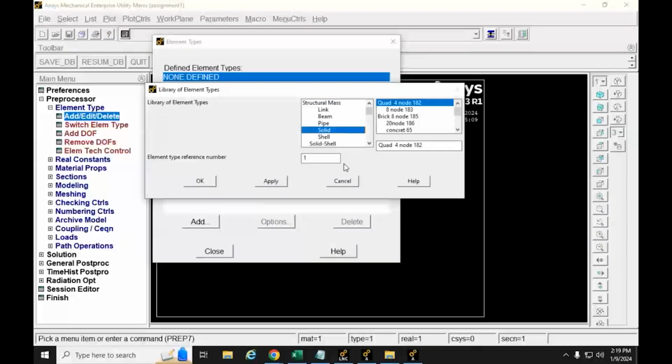The solid element is for solid structures, so 3-dimensional structures that we want to mesh, and then shells are for very thin sheets that we want to simulate. If you scroll down below this, they've got contact elements, gasket elements, cohesive elements, and then you'll see combination element there, which we're going to be using, and then below that is thermal mass.